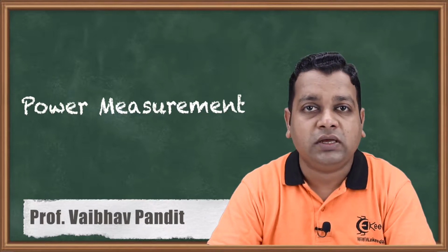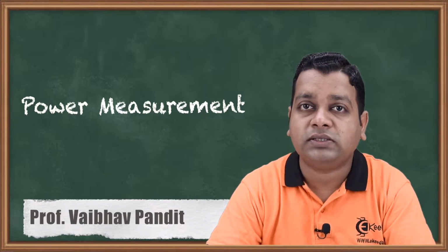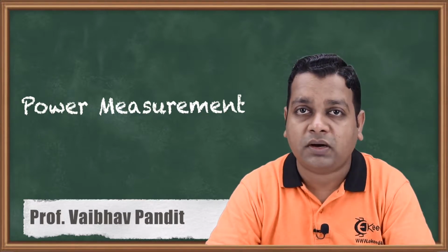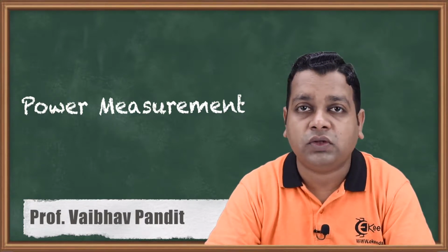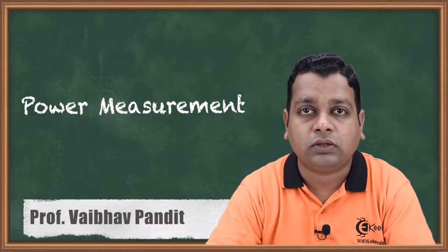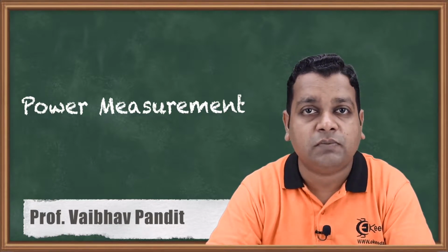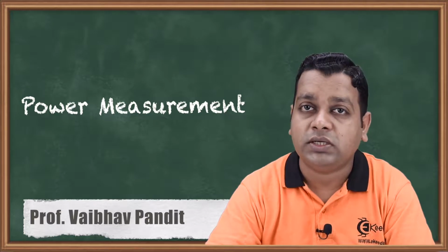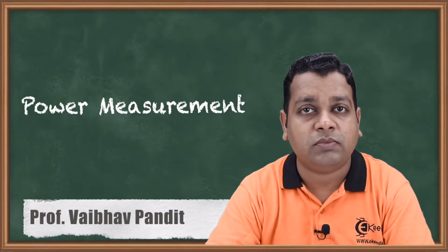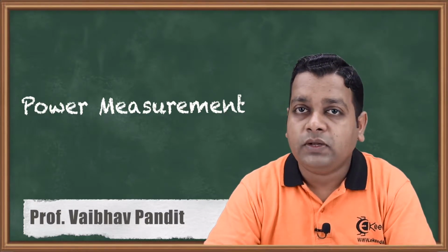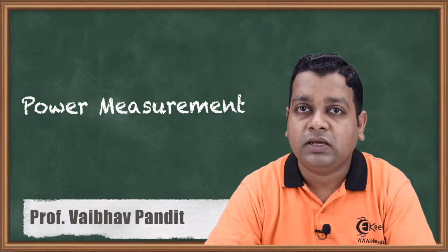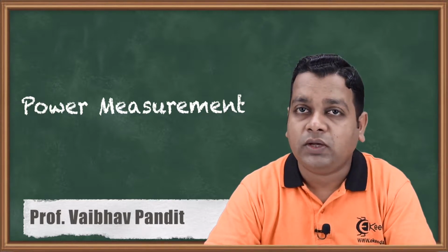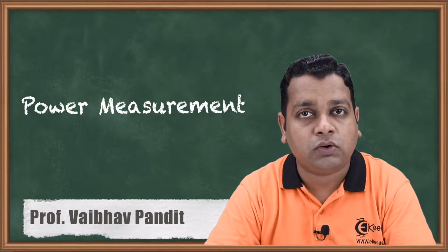We started to see how the measurement techniques at the microwave range are different as compared to the low frequency measurements. We have been introduced to the very important devices or components with which the measurements are made possible. These are the slotted line and the tunable detector. In the previous videos, we have covered the VSWR measurement techniques, VSWR standing for the voltage standing wave ratio, and we have selected 4 problems solved onto it.